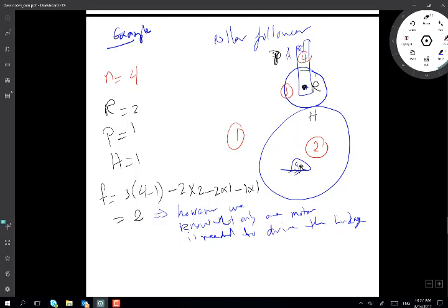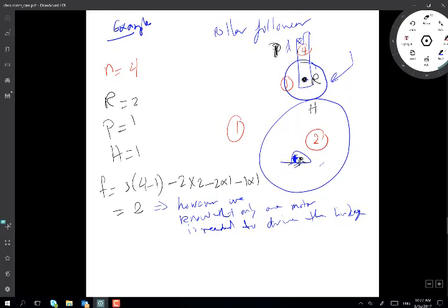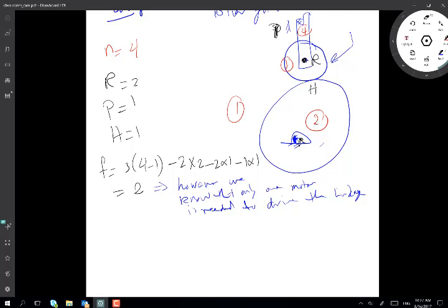The number two we're getting here, we can look at it as one real degree of freedom, which is the motion about the center point. But we also have another freedom, being the motion of the roller. The roller can rotate at any point in time. You can fix everything so that everything becomes stationary, then start spinning the roller about its axis, and it will be able to spin because it's round. So this is an extraneous degree of freedom that doesn't affect anything.